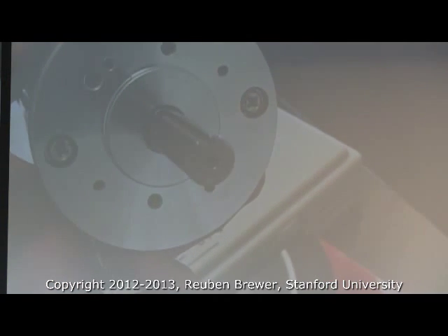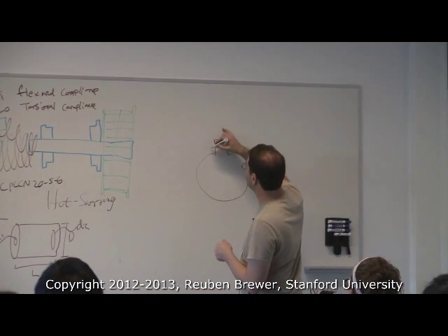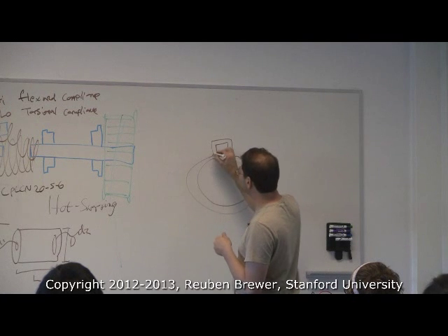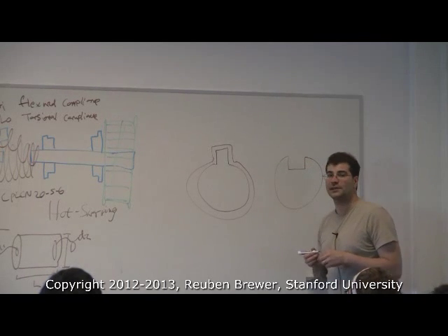Okay, this looks good. Everyone see that there's a little nodule on that, the black nodule on the shaft. So that gives us positive engagement with a pulley. And then here, you see the notch cut out of the shaft there? That's basically the negative of that, where you install your own key. So let's talk about how that works. It's called a key, like a key to a door. And it will either come on the shaft already, like this, and so then your pulley shape will be like this, or it will be the inverse, where it comes like this, and then you hammer in your own key.